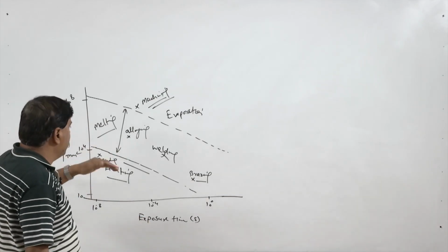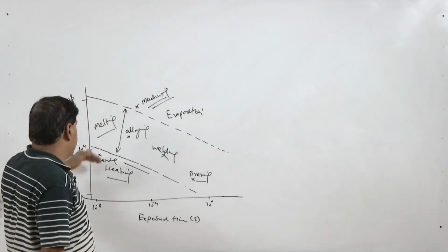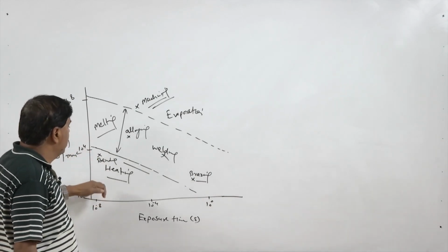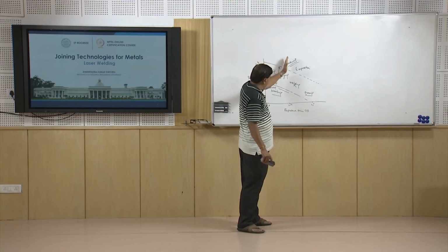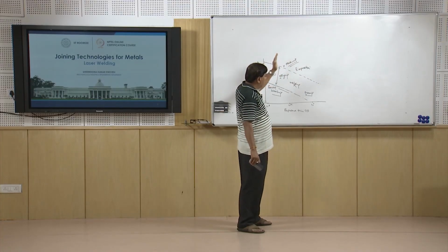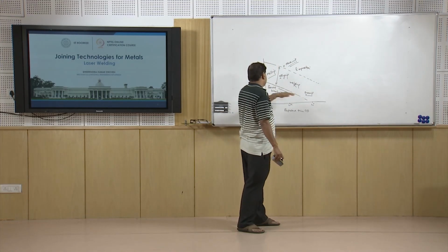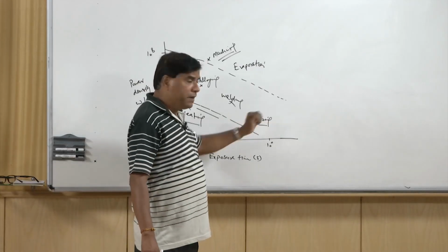So basically if higher is the power density, we need a shorter exposure time for generating the heat. Depending upon the purpose of using laser, we may use it for a very short period, just for softening purpose, higher power density for short period, and somewhat very high power density for somewhat longer period for the machining or the cutting purposes, and for the laser for the brazing purpose lower power density and the longer period.